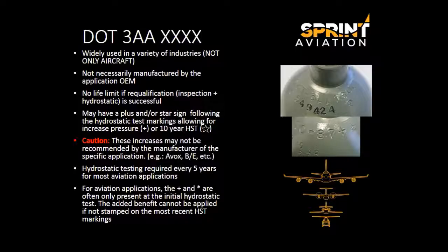Canadian operators should refer to publication CSA B339 for more details on this. Take note that these increases may not be recommended by the manufacturer of your PCA, such as Avox or BE. Hydrostatic testing is required every 5 years for most applications.